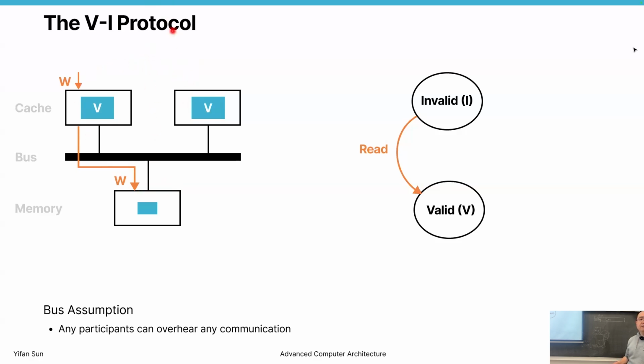We have to have some other messages to notify that something happened. We call this a processor write, PR write. I'll mark it later. You'll see other examples. On the other side, we are generating a bus write. Bus write means we're writing to the memory, and this write action is written into the bus.